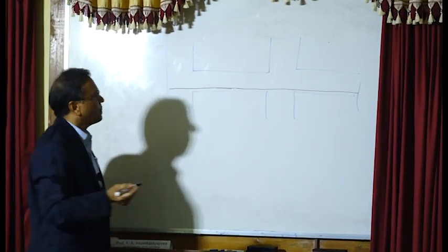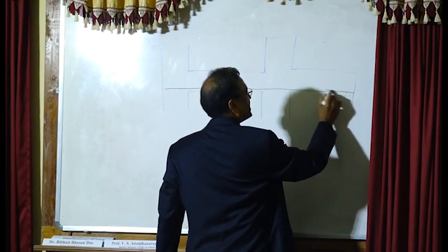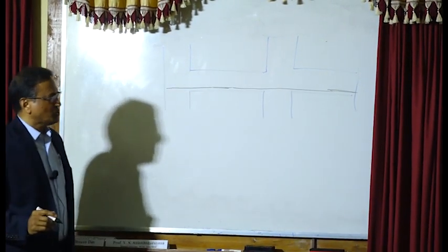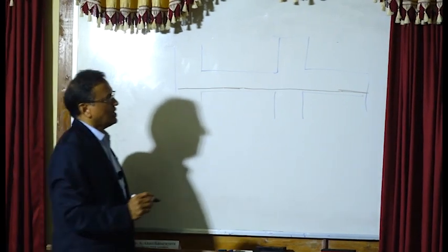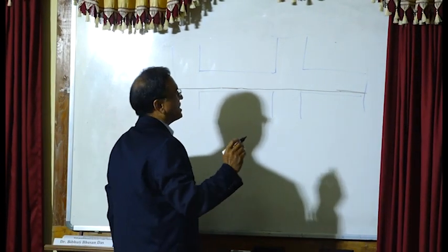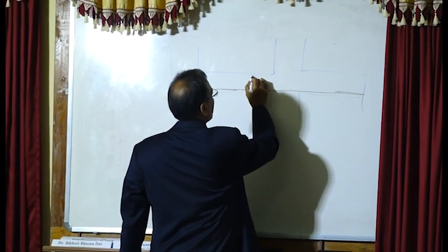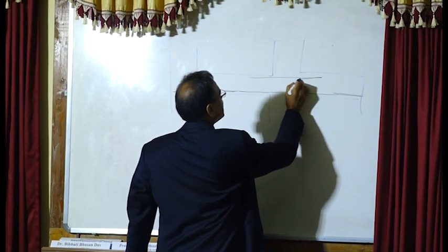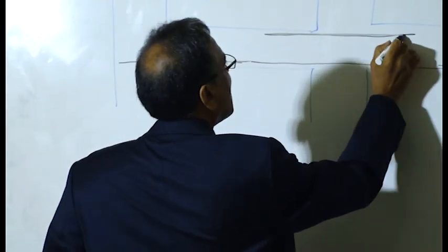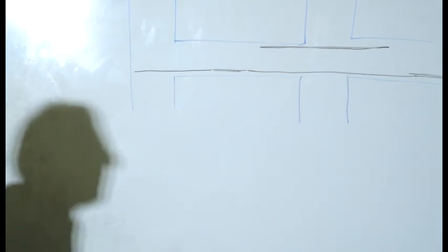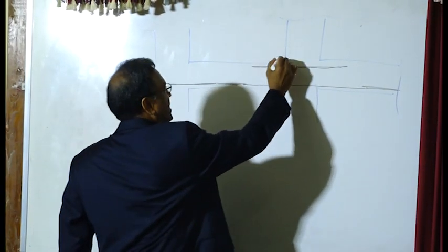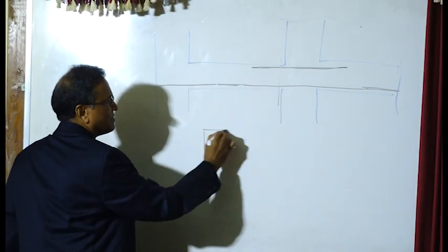We all know that. Around here it's in tension. So those two areas we can use the tensile capacity of FRP bars. But what if you have a bar here? Is it going to tension or compression? Tension, definitely.